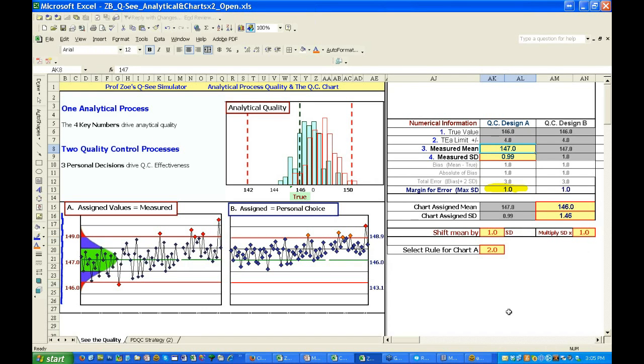So Rick, why did the mean change? What causes that mean to change? Technically, if you're running the method, you come in and oh my God, the mean has changed. What would you look for first? What are your typical causes of a shift in the mean? Mechanically, it's a restriction in the sampling circuit. It's short sampling, for instance, and it could have been short sampling when it was calibrated, and meanwhile that restriction is now gone, and now it's getting a much larger sample, which is causing your mean to shift upwards.